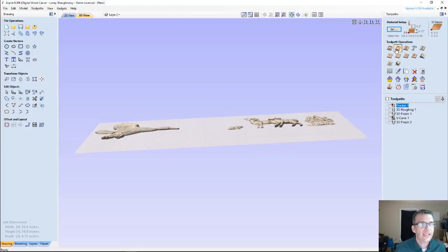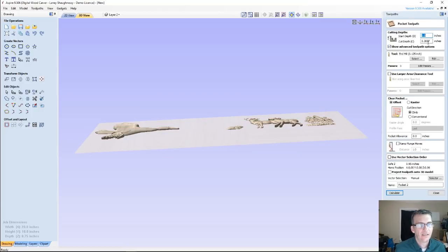So when I'm coming in to create a pocket cut, I have to take 0.75 minus 0.4463 equals 0.3037, because that's what that pocket depth is. That's the depth of that pocket. It's the depth of the pocket no matter what.